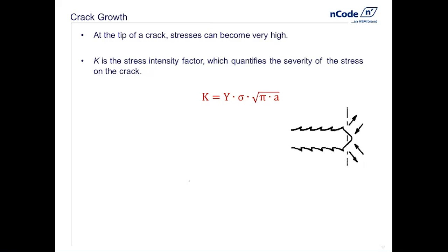So we have to think now about, if we have a crack that starts microscopically, it can grow to become large enough to be what we'd call an initiated crack, or a macroscopic crack, a couple millimeters, so it's a macroscopic detail now. The stress at the crack tip can become very high. As a matter of fact, if you use elasticity theory, you can show that a crack will have infinite stress on the tip,